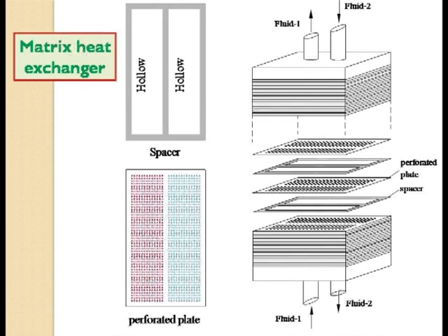Now axial conduction will be very high because copper has a very high conductivity. To minimize the axial conduction, in between you should put stainless steel, whose conductivity is somewhere around 10, 12, 14 watts per meter Kelvin compared to 400 watts per meter Kelvin for copper. So compared with the conductivity of copper, stainless steel becomes an insulator. Because of that, by using this spacer, we are minimizing the axial conduction effect.